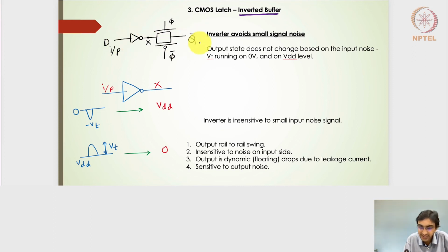So I will actually get a complemented latch output. And let's say that for the time being it is perfectly fine. I don't really care about getting a complemented or an uncomplemented logic. So if D is 1, the Q bar will give me 0, and if D is equal to 0, the Q bar will be 1 in a transparent mode, right? And by definition, in the opaque mode, whenever the clock is at low level, the Q bar should be retained. Whatever was the Q bar in the previous high level of the clock, it should be retained.